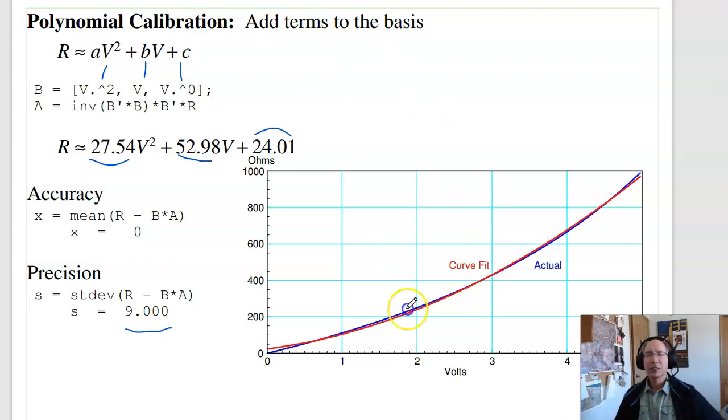That's basically calibration. Take something that you can measure, like voltage, and from it, tell me something that I want to know, like resistance. Or for various temperatures, or various sensors, I could find temperature, light, strain, pressure, flow, whatever.